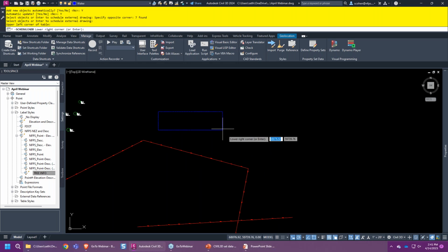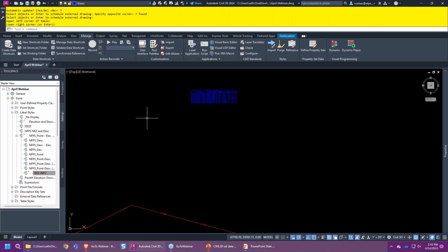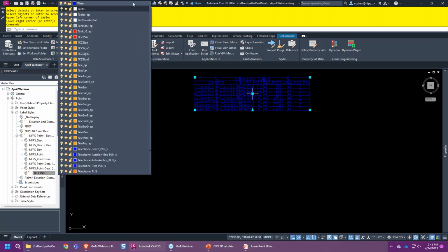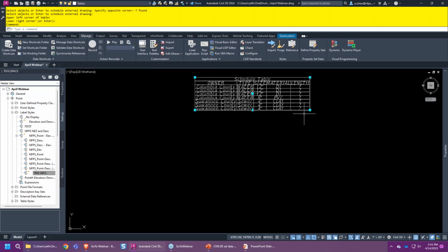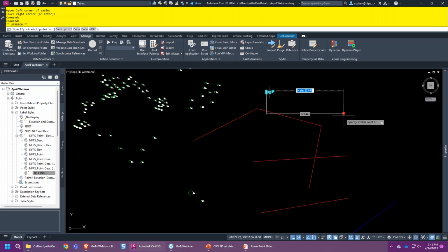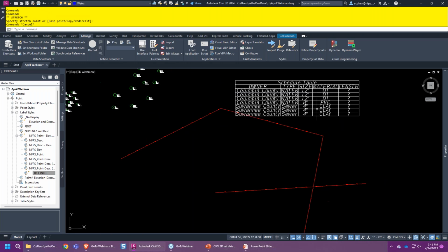It's kind of weird as it does let you size the whole thing the way you want to, but normally you would just press enter here because that's the size you want it to be. It's a one-to-one table, and you'll use a viewport to size it one-to-one. It does put it on the current layer, so I'll set this to the correct layer. I have a tables layer in here, and we'll click on that, and there's my layer. Now, just for presentation purposes, I am going to make this a little bigger, just so I can stay zoomed out.